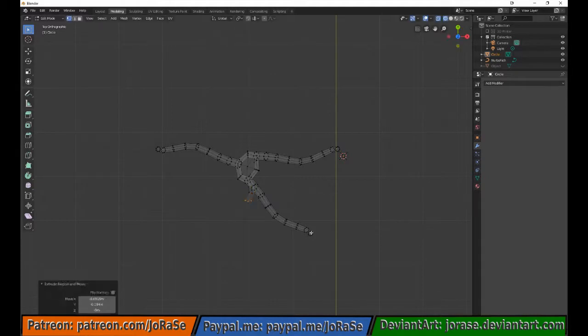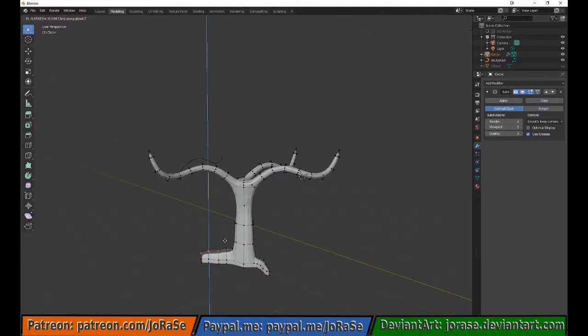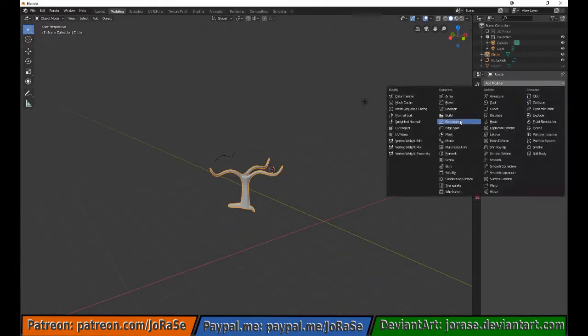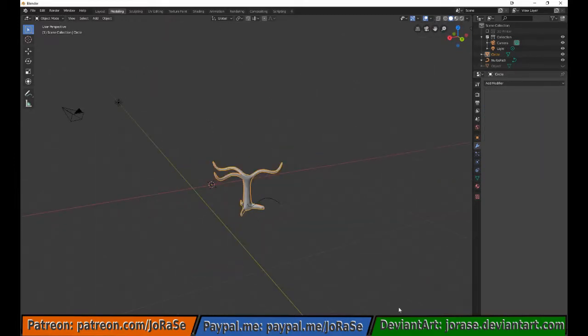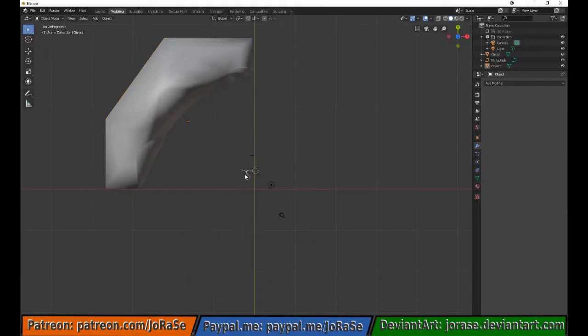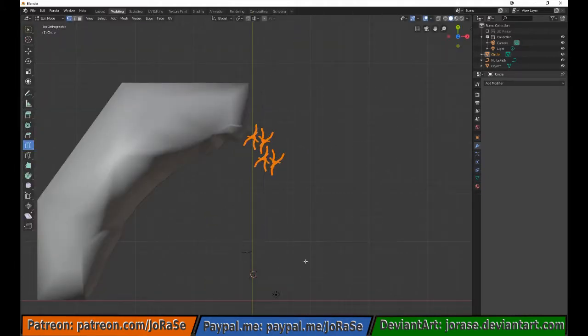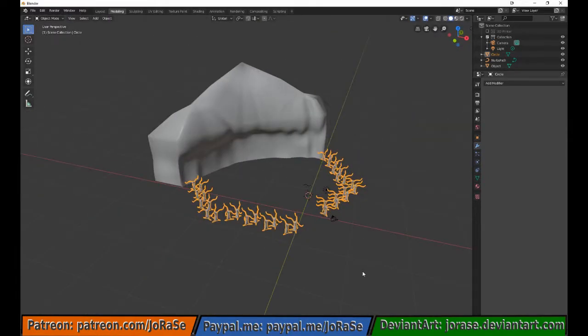But let's add in our roots, because that's something we definitely need on a tree. Alright, that looks pretty good. Fill in the bottom faces on everything. And yes, I did do a subdivision surface to make everything look a bit better. And now we're doing a decimate, which removes some of the subdivisions, so you're not dealing with so many faces per model, but it will keep the same general structure. And now we're getting our little forest area built, which will enclose our town along with the cliffs.